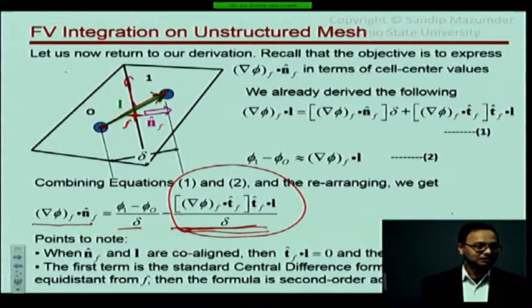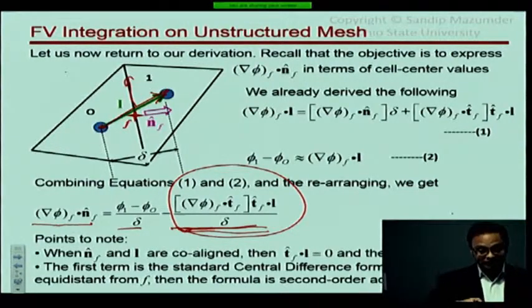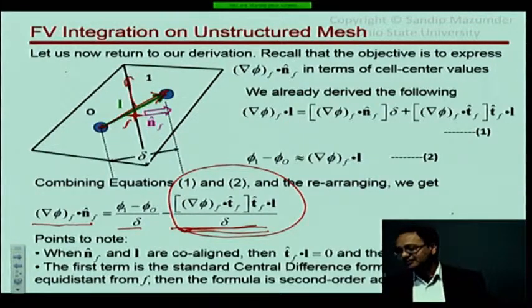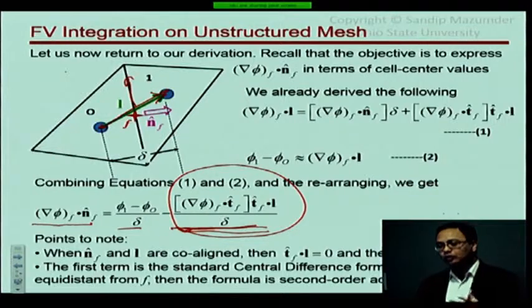Okay. And where does that lead us? That leads us right to the basics: if you have a bad mesh, you'll get poor convergence. Because that term will be treated explicitly, it will slow down your convergence. There are very few codes in this world where that term is treated implicitly, because if you actually try to write it implicitly, you'll see that you have to extend your stencil. It becomes pretty difficult, at least in a finite volume or finite difference formulation. Okay, so that's the reason, it all goes back to your mesh generator in the end.